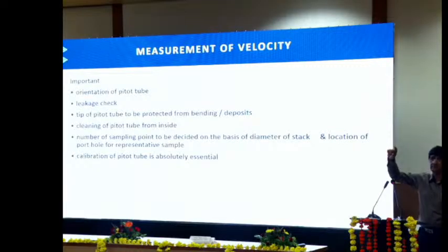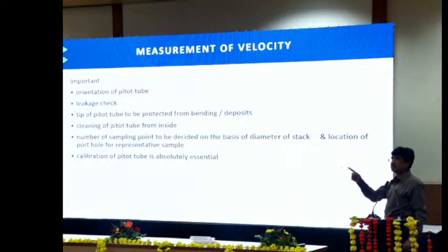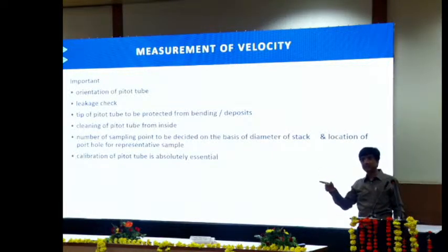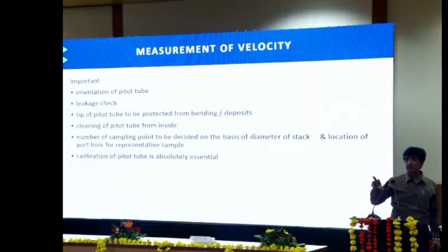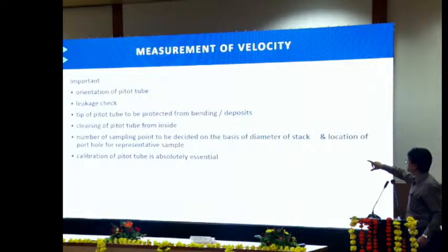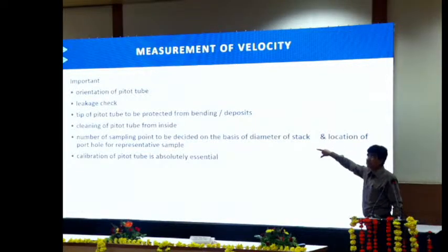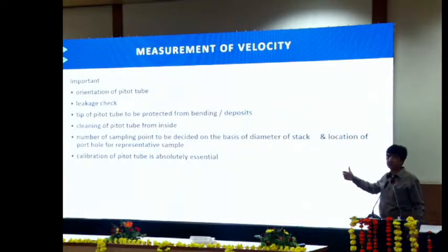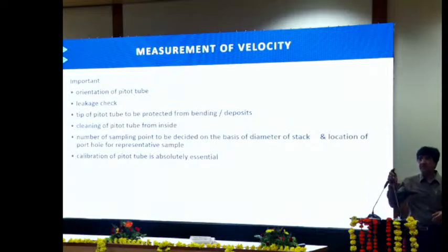Multiplied by 1.5. So basically that 52, another into 1.5, you need to add 26, it becomes 78. So basically you then need to collect the sample at 78 traverse points. All these particular things become very relevant once you are going for the calculation. Is it clear?